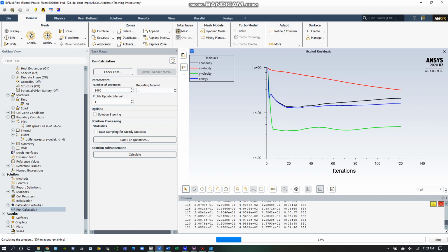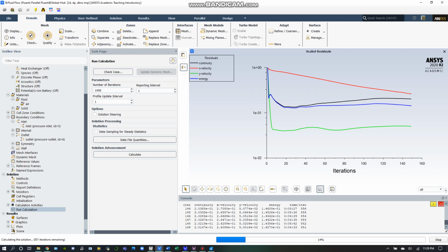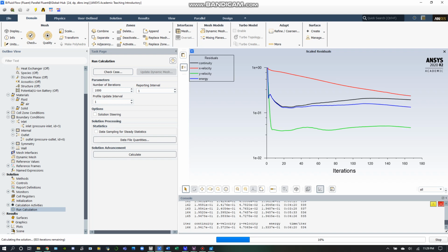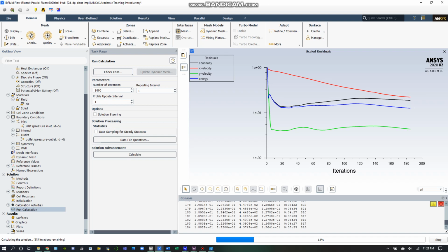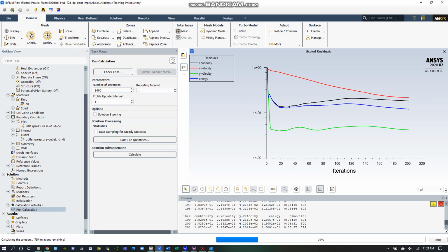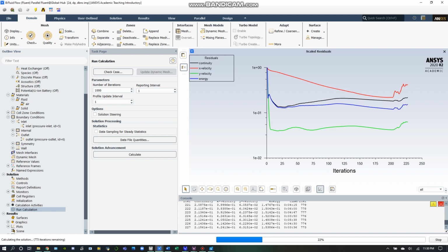Again here, I think we need to remember that the mesh was very important for this process, and I increased the amount of elements for one of my trials, and it was around 200 something thousand elements, and it actually did not converge, and it did not look very good. So I needed to redo the mesh, and it was through watching tutorials and various YouTube videos that I found what I believe worked best for my case. This is going to take just a little while because my computer is not the fastest.